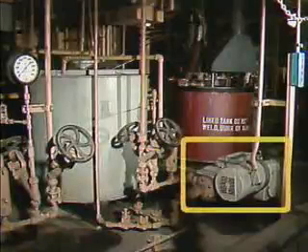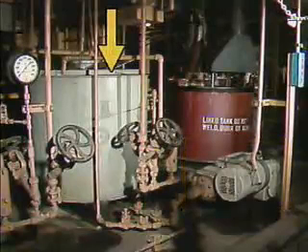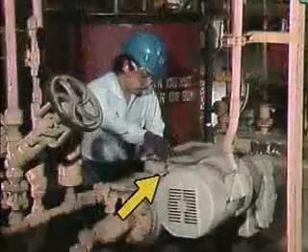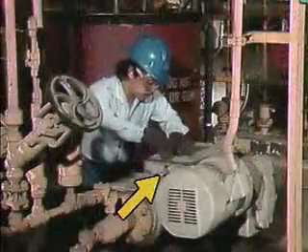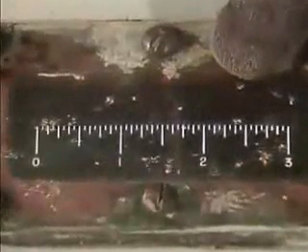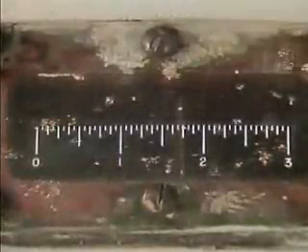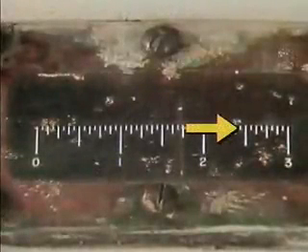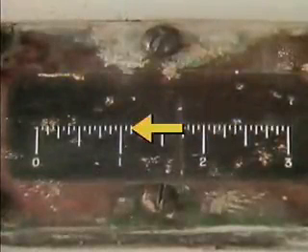For example, this is a chemical injection pump. A chemical is stored in this tank and fed to the pump. A stroke adjustment is used to adjust the rate at which the chemical is fed into the water. Adjusting the stroke lengthens or shortens the stroke of a piston inside the pump. A longer piston stroke increases the rate at which the chemical is injected, while a shorter piston stroke reduces the chemical injection rate.